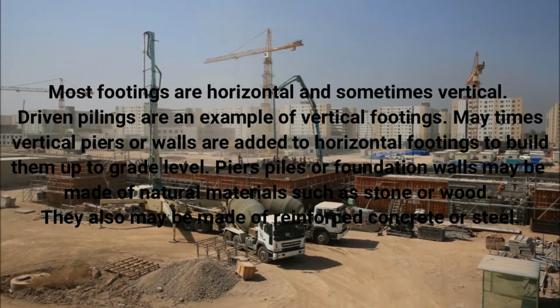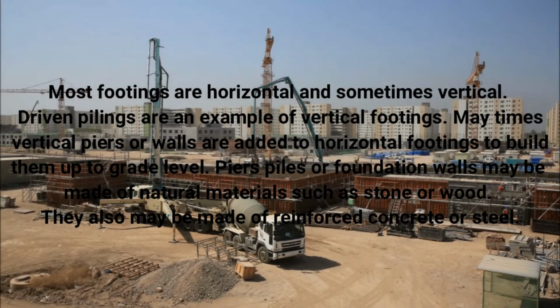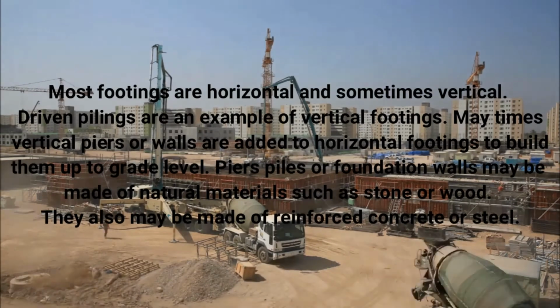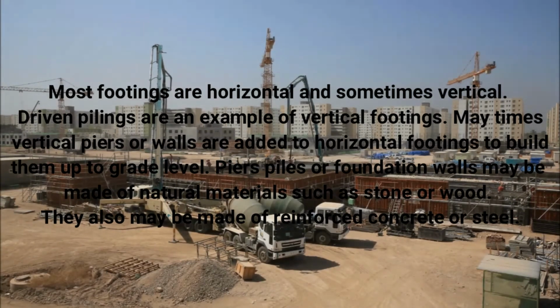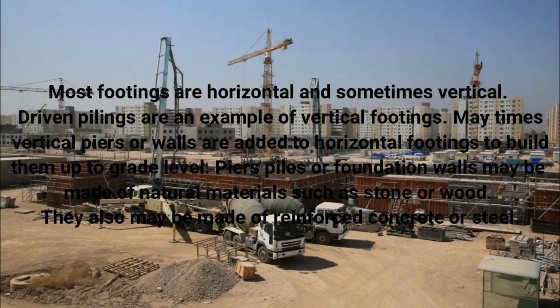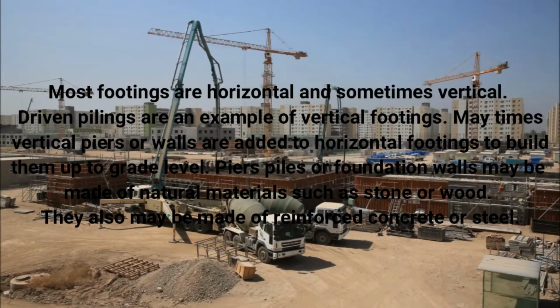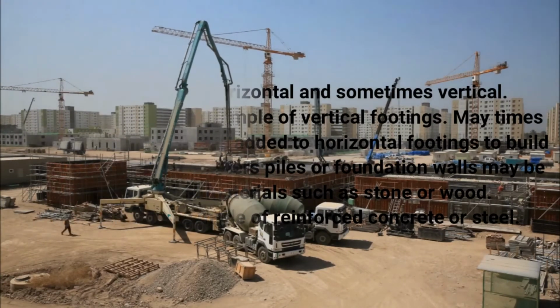Most footings are horizontal. Sometimes, footings are vertical. Driven pilings are an example of vertical footings. Many times vertical piers or walls are added to horizontal footings to build them up to grade level. Piers, piles, or foundation walls may be made of natural materials such as stone or wood. They also may be made of reinforced concrete or steel.